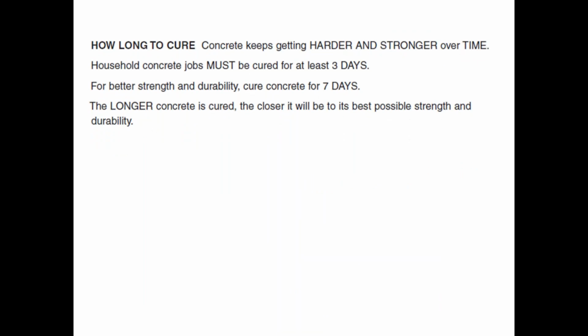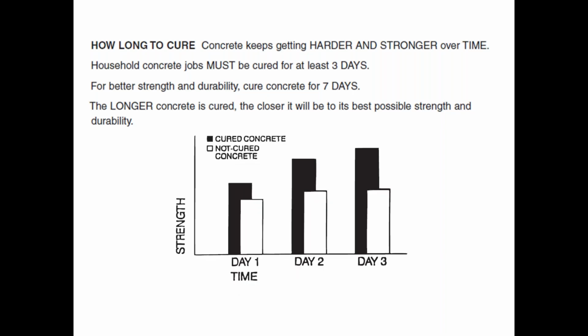And the question is, everybody says again, well, is it 3 days, is it 7 days? How long do you actually do it? The simple fact is, the longer you do it, the concrete just gets harder and stronger over time. So if it's a household job, they say about 3 days, but for better high strength durability or a big commercial floor, one would argue you do it longer, for 7 days if you can.